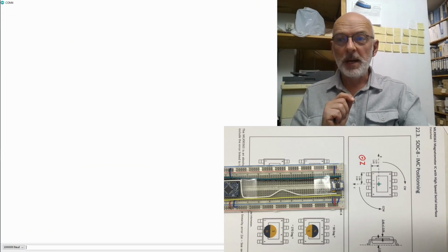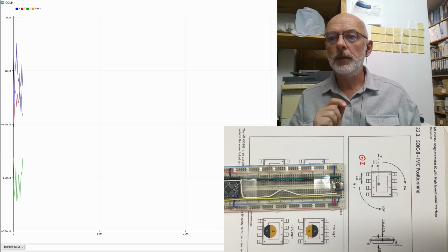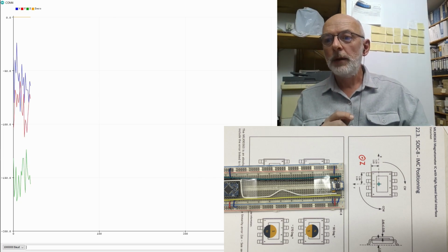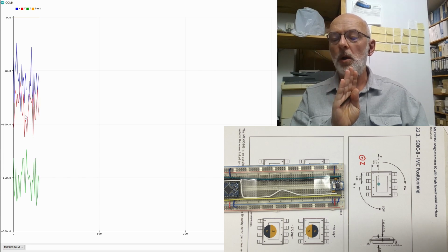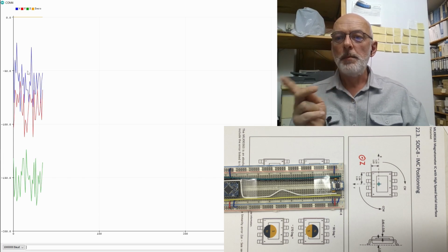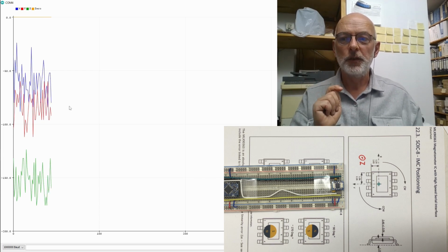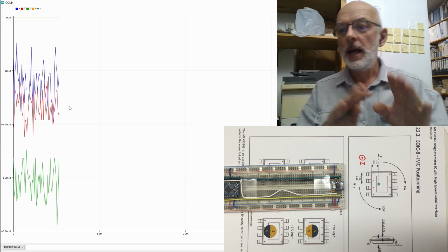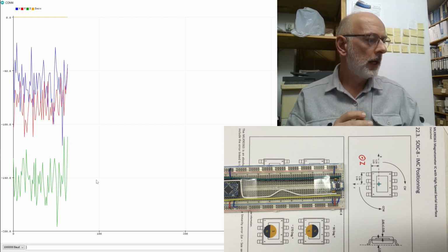So let's measure. Press enter to start, and what we can see here right away is that I don't see my zero. My zero is at the very top, and we have here comparably small negative numbers. Remember, these values here are signed 16-bit integers, so approximately plus minus 32,000. And we are here now at green, that's the z-axis, at minus 150.